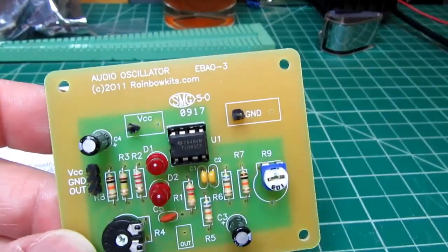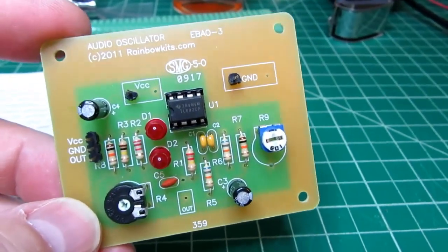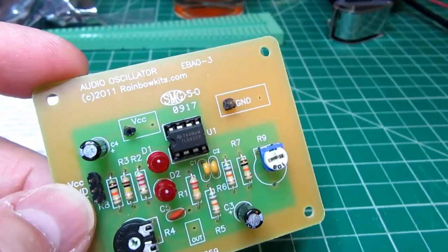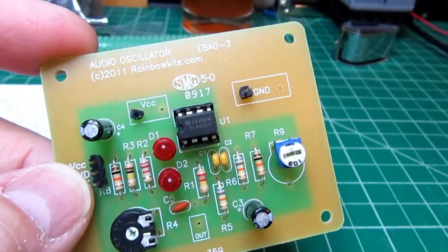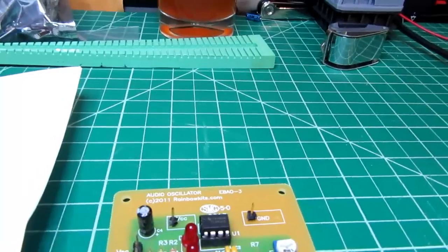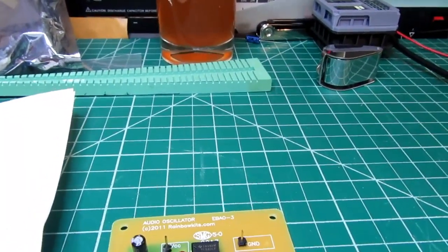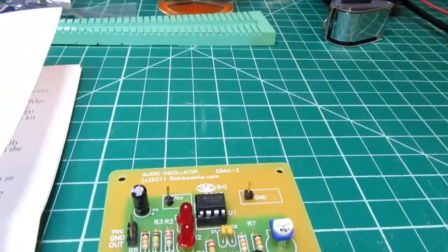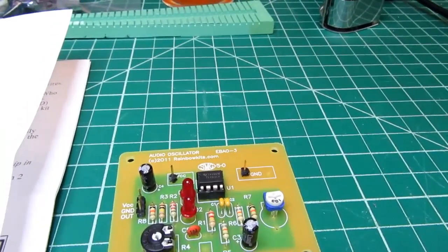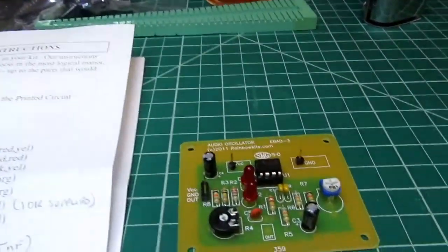They are very different op-amps, although in a simple low specification circuit like this they're interchangeable, but the TL082 has got better specifications. It's a more modern design. 1458 is really just a dual 741, which also would be fine for this circuit, and that's what the parts list says. But again, it's kind of odd they didn't update their manual with the part they're actually supplying.